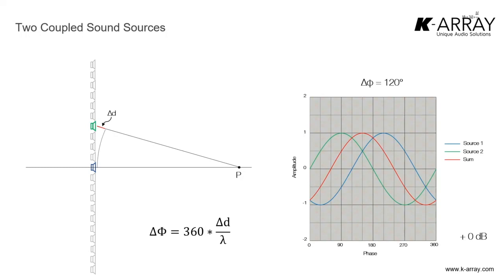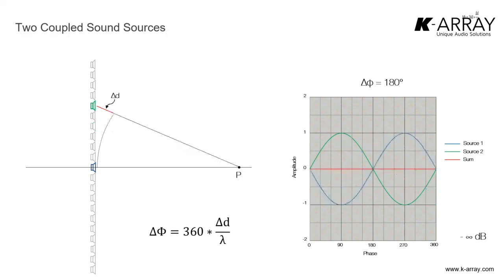But things can get much worse than having a useless woofer. Because, as we all know, if the difference between the two distances from the microphone is exactly half of the wavelength, or close to half of wavelength, I have a deep cancellation. So this woofer here, it's destroying the SPL that the one on axis is trying to create, of course, at the frequency that we are considering.